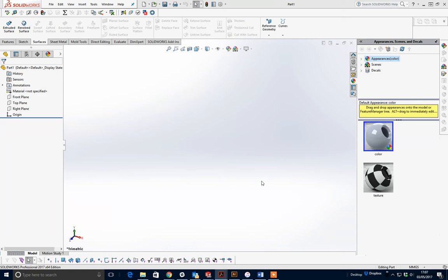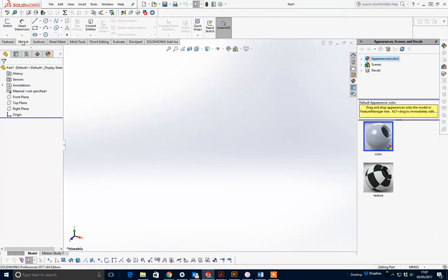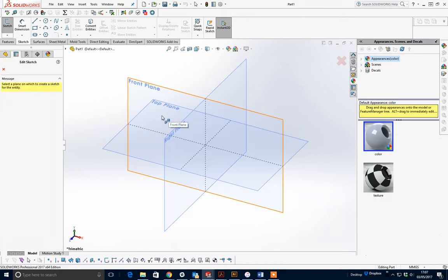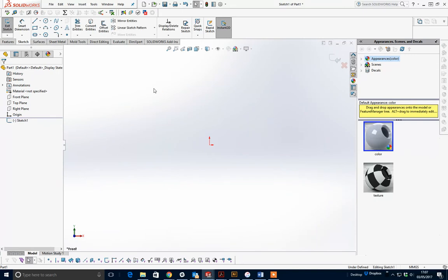Okay, you should have the bracket sheet in front of you. So again, you've got the SolidWorks screen. I'm just going to open up a new drawing there, sorry about that one. As we said, everything starts with a sketch, so I'll go up to sketch on the left hand side, and this time I'm going to pick on the front plane.